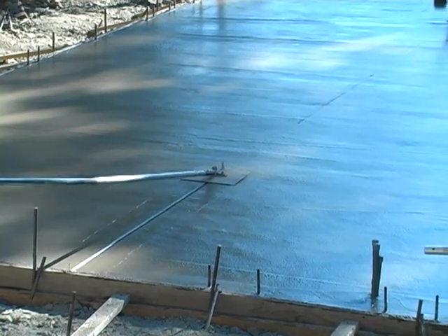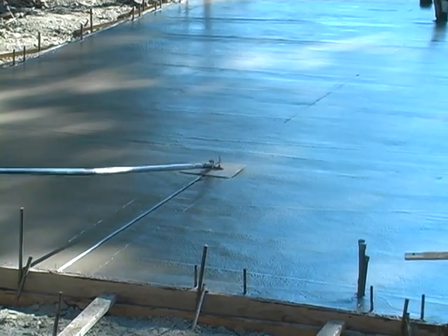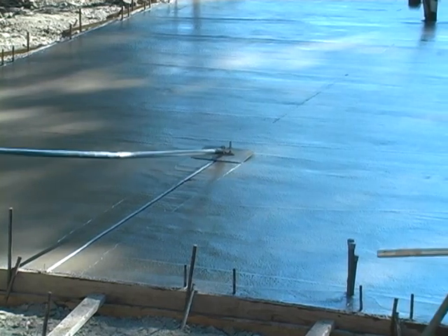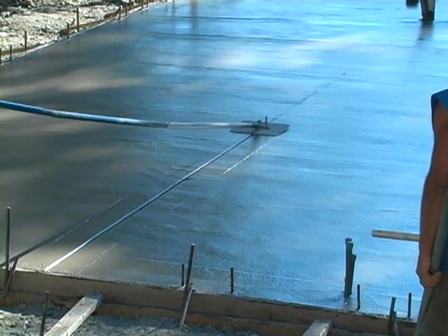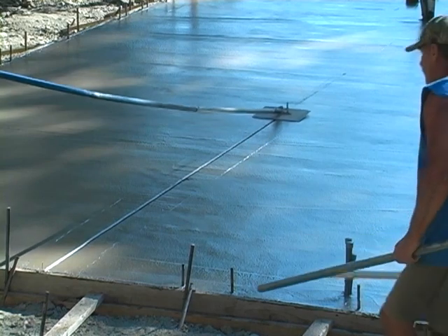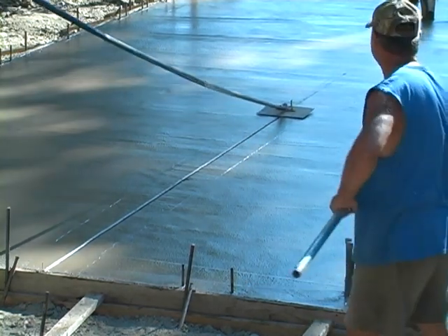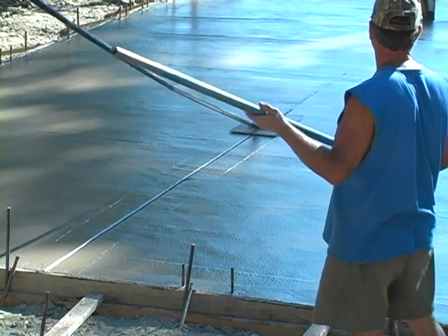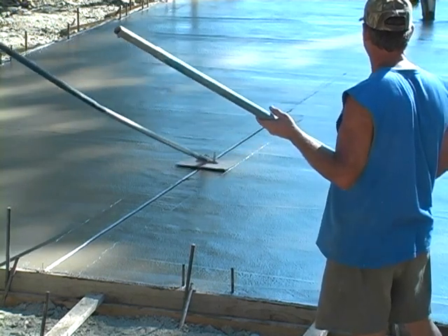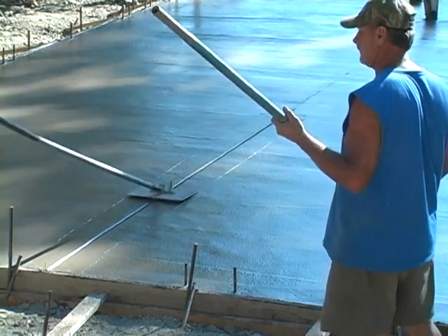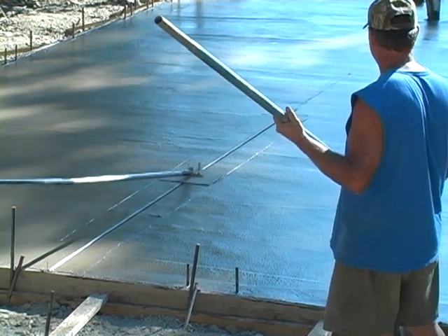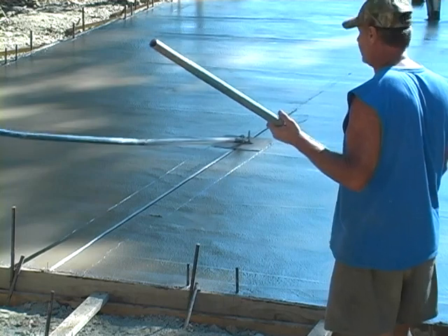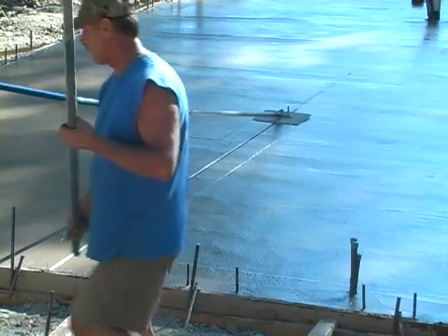You're pushing wet concrete out of the way with the grooving tool, especially if you have a long run to go on. It can be a pretty difficult task to do. Now you can see there's a slight line ahead of where we're pushing our grooving tool right now, and we'll use more and more extension handles as we get out there further into the field. The line that we're following is just simply a snap chalk line that we do ahead of time, which we'll show you a little bit further into the project here, how you can do that.